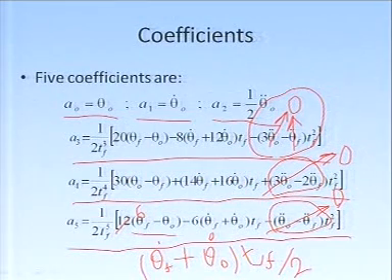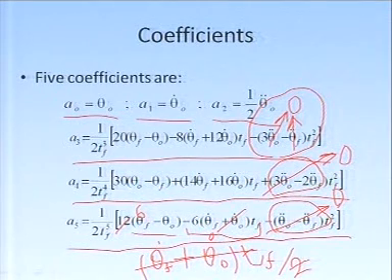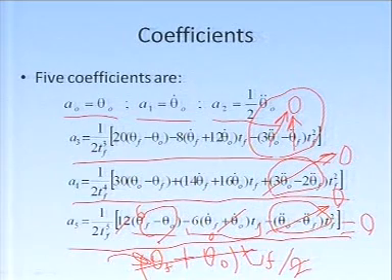Okay. So, this cancels out. So, then it becomes 6 theta f dot plus theta 0 dot into T f, which is exactly the same as this one. So, then this term and this term will cancel out, giving a result of a5 is 0. So, what did I get? If my end accelerations are 0 here and if I choose my theta f minus theta 0 in this fashion, I get a5 equal to 0.